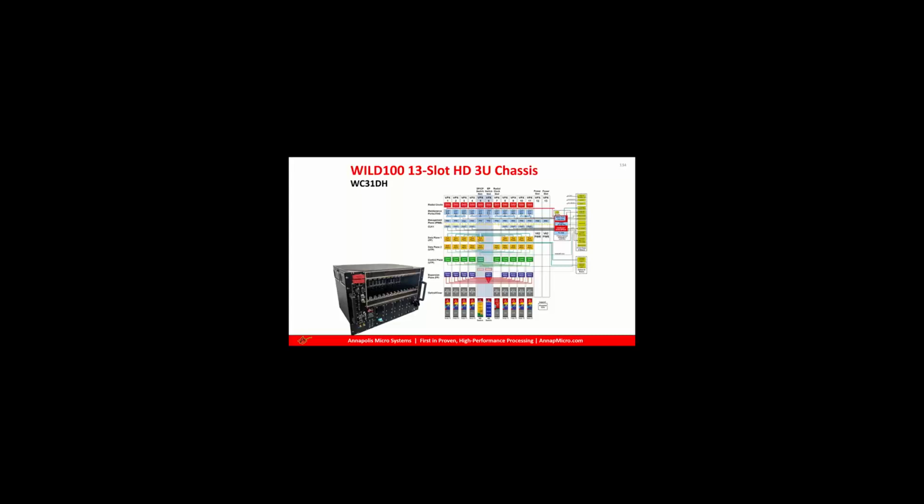All those slots are standard OpenVPX slots. The 2 blue ones are the new slots that use this new connector. So those are the switch slots. One connects up the data plane and control plane. So that would always be Ethernet. Ethernet is the only protocol that's allowed on those.